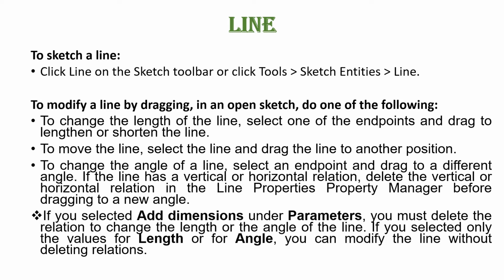First, we will go for line. To sketch a line, click line on the sketch toolbar, or click tools, sketch entities and line. So there are two ways to select the line. First is the sketch toolbar. Second one is tools, sketch entities and line.